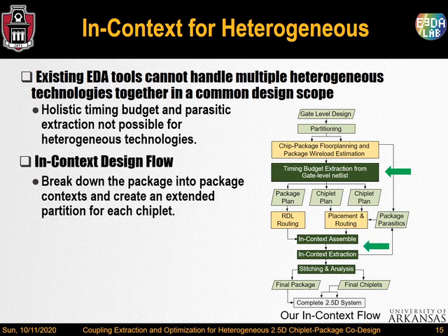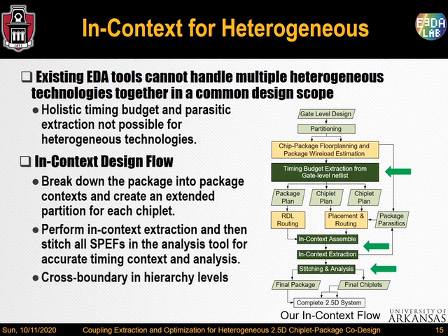After physical design, each chiplet is individually assembled with its package context, and in-context extraction is performed on it. All the extraction SPEF netlists are stitched together in the analysis tool for timing context creation. These timing contexts are used for iterative optimization and sign-off verification.